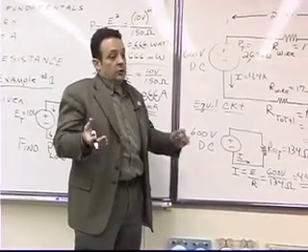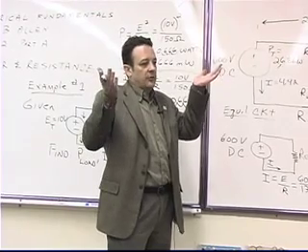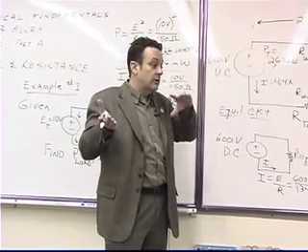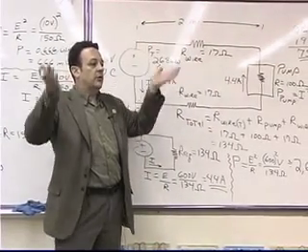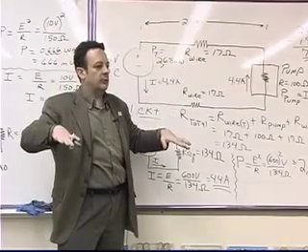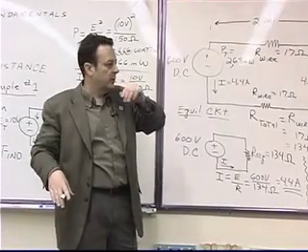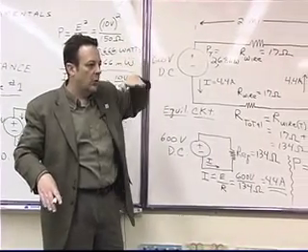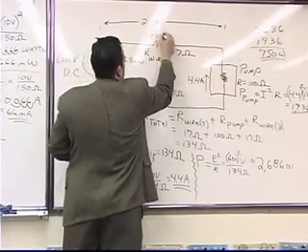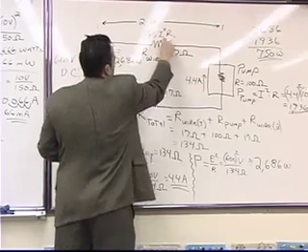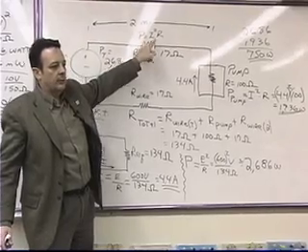One way would be you could buy an inverter, you could step the voltage up, and then by stepping the voltage up, you would reduce the line losses. Because by stepping the voltage up, the current decreases in direct proportion. Right? So if the voltage goes way up, the current goes way down, and then the power, which is equal to I squared R, that's the power lost in that resistor, goes way down because the current goes way down.